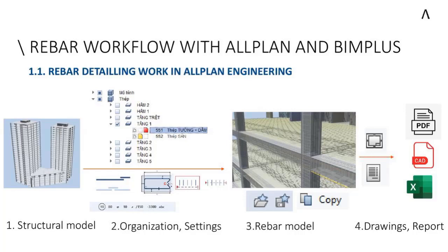After you have the structural model, you will set up the file settings to prepare the rebar, and after that we can use some functions and create the rebar for the model in Allplan. And finally, we will export the report for the schedule of quantity of concrete and reinforcement, and make many kinds of drawings in PDF and AutoCAD format.